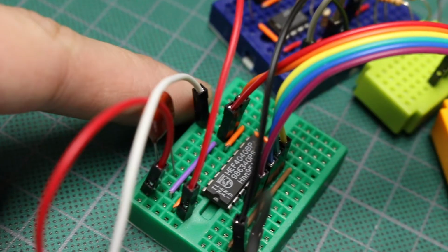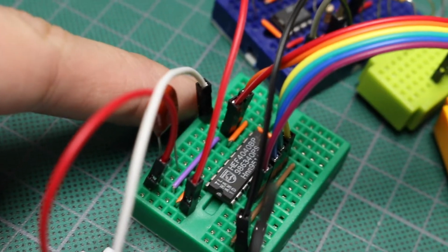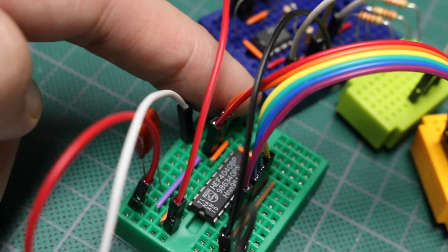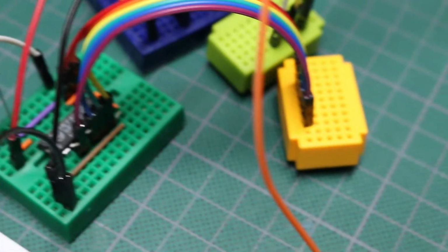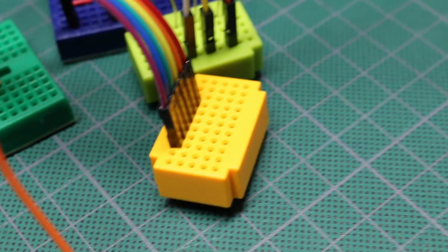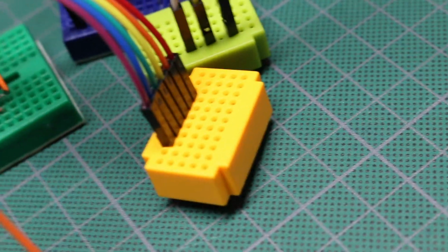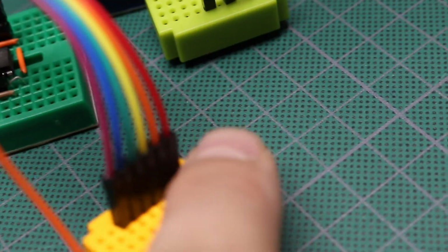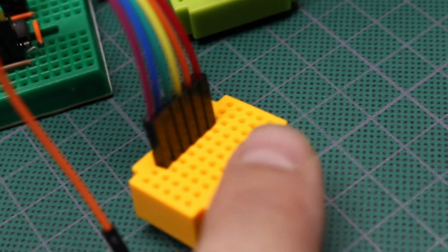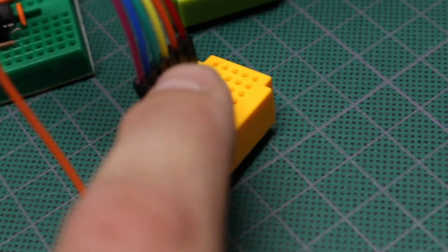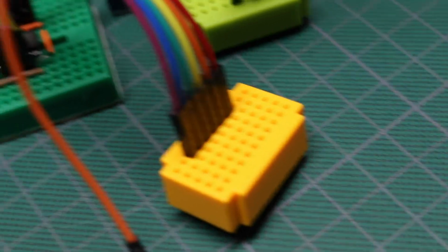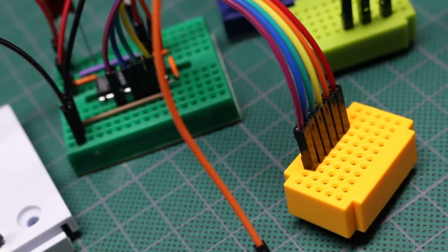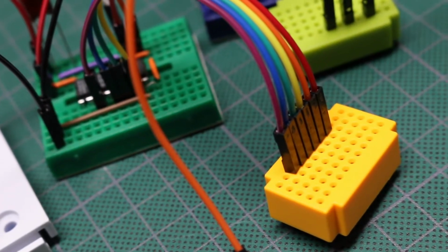So the main clock from the 555 comes to the clock input of the 4040, and then I tapped into the first 5 or so Q outputs, and I brought those over to this little breadboard so I could easily tap into them. So starting up here on the right would be the main 555 clock, and then each one going left is Q0, Q1, Q2, etc., dividing down the main clock by half each time.